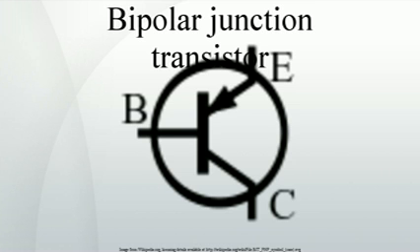Etymology of hFE. The h refers to its being an h-parameter, a set of parameters named for their origin in a hybrid equivalent circuit model. F is from forward current amplification, also called the current gain. E refers to the transistor operating in a common emitter, CE, configuration. Capital letters used in the subscript indicate that hFE refers to a direct current circuit.